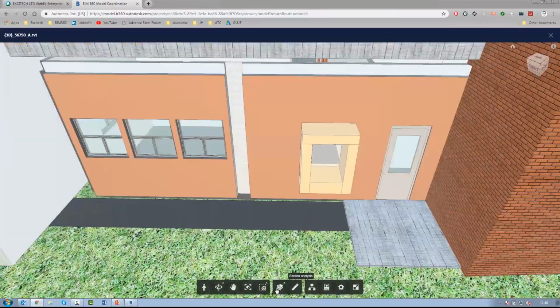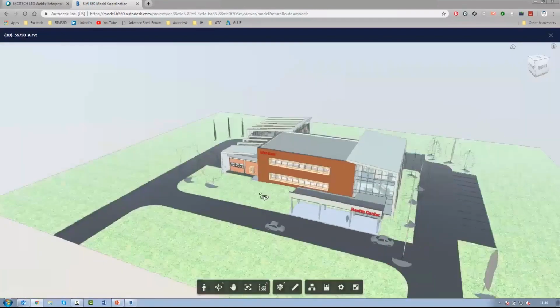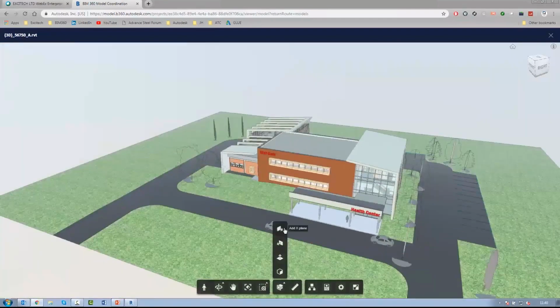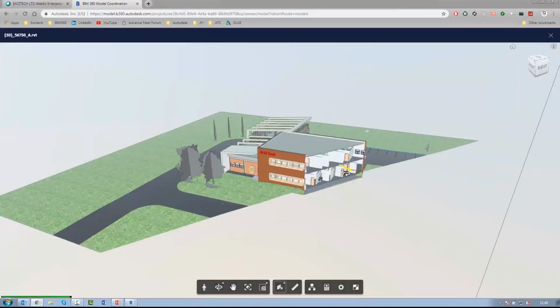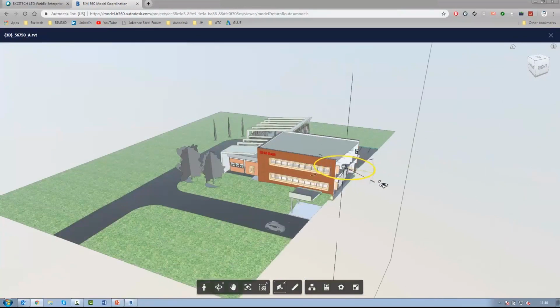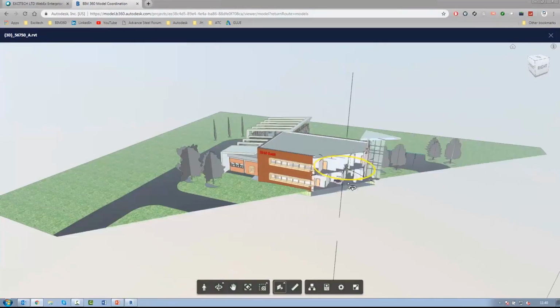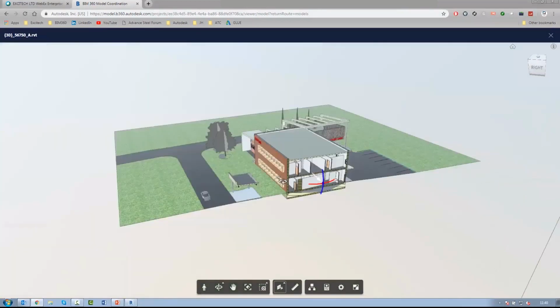There's also a lovely tool called section analysis, and this will allow me to create sections and cut the model. If you select it, you've got sections on the X, Y and Z planes. If we put the X plane on, you will see that you get a little icon where you can use the arrows to drag, and as you drag, it's cutting a section through. You can use the little widget to orbit the actual section in the X direction, and again you can then orbit it.